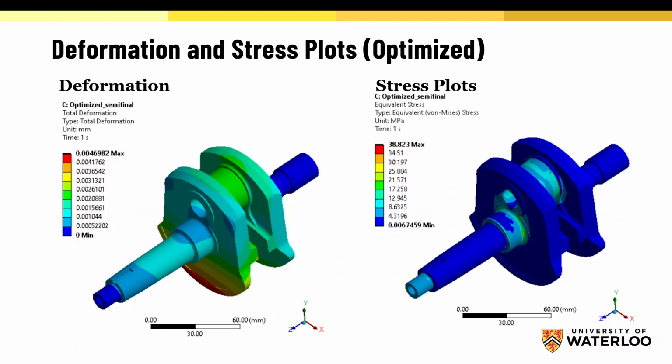Because maybe you're overestimating the source. Maybe you're saying that this is a 30-watt device and it's not dissipating enough, but is it really truly operating at 30 watts all the time? That type of thing. Is the enclosure, the ventilation around the enclosure, something that you're accurately modeling compared to the test setup? Or is it just in stagnant air that's not moving? So is there free convection? Are there things you want to investigate?